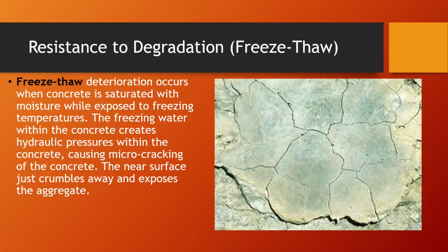Then it thaws, but now you've got a slightly bigger hole than the night before. And this process continues and continues, and then it starts to actually break up the concrete. It starts to crack it up, and of course, as it starts to crack, it allows more water in, more freezing, more cracking, and then we've got some unraveling of the road surface or the surface of the walls of a bridge or a tunnel. So it's very important that we make sure that we get these pockets out.